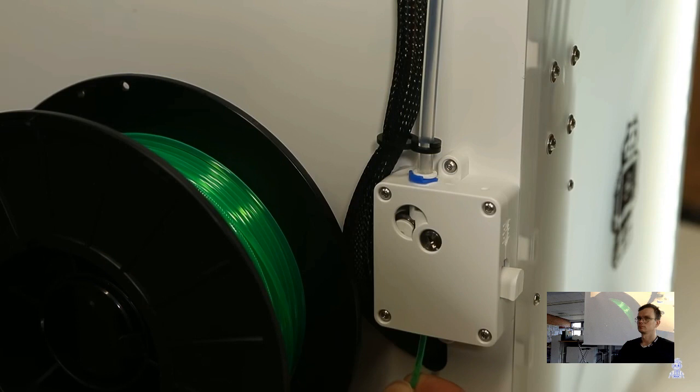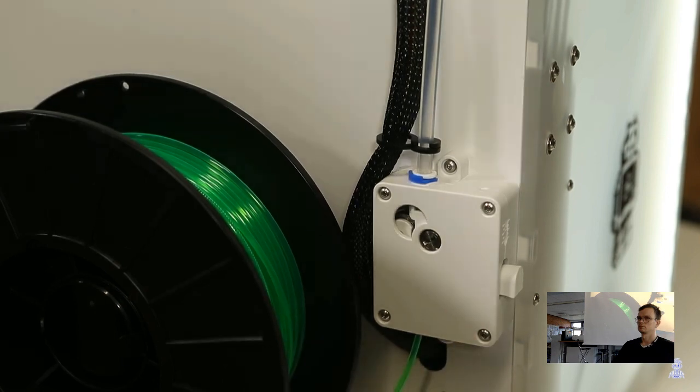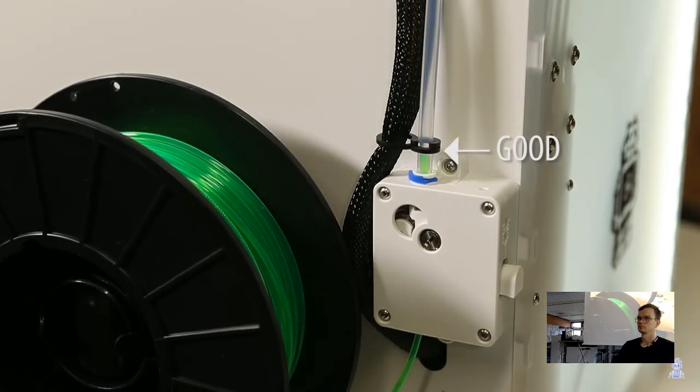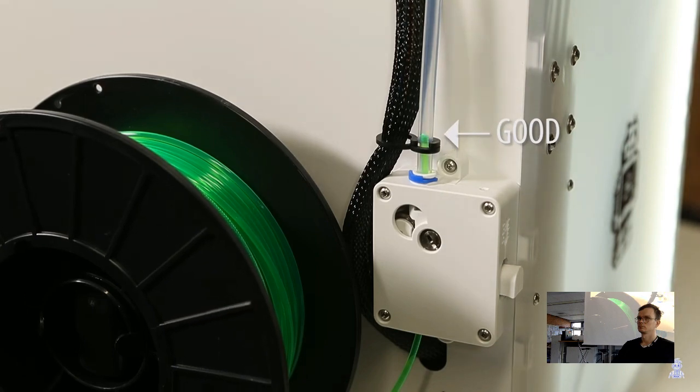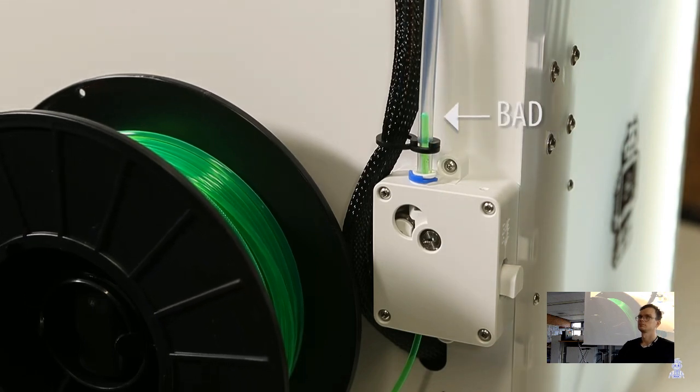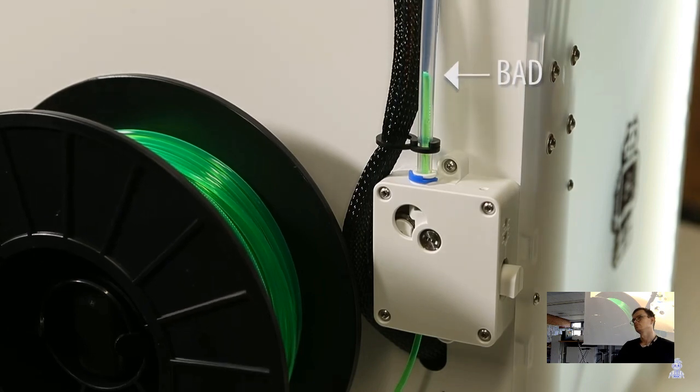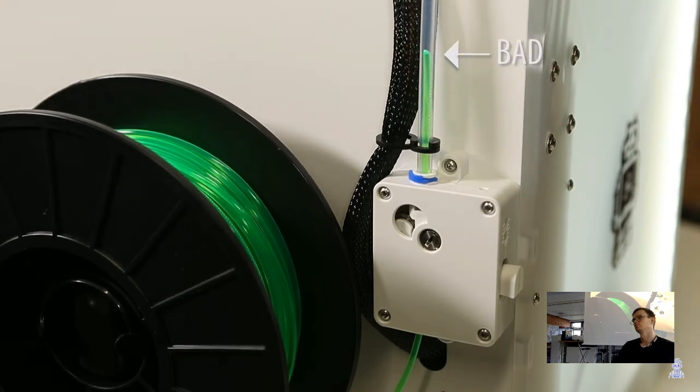In order to insert filament, you're supposed to insert it through the back where the geared motor is, and then you wait for it to appear in the Bowden tube, and then you hit a button and it fast forwards that filament, jamming it into the hot end. If for some reason it gets a little too far into that Bowden tube and you advance it using the button, then it's going to jam the filament into the hot end and keep driving, grinding away at the filament, creating a space, and then you have to pull it out, snip off that bit, and try again.